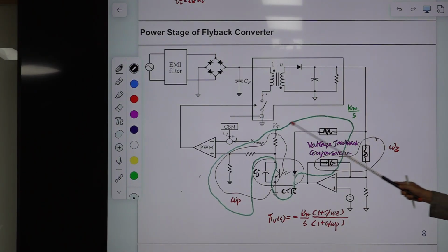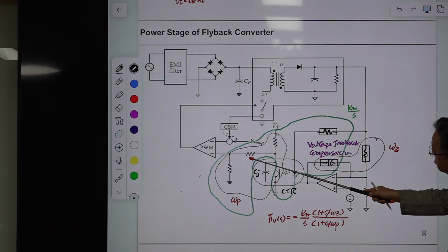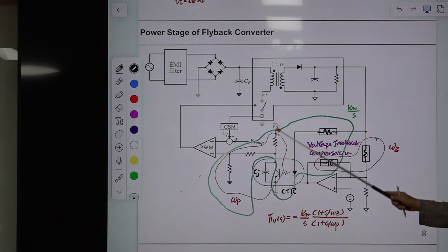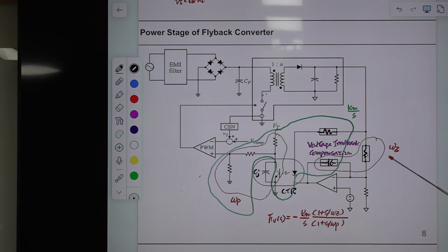Later on, you will do simple circuit analysis, very simple, and this creates 1 zero, and there is a C. This is the parasitic capacitance CJ involved with this phototransistor, and this is combined with this resistor, this resistor. Then there is one pole here.